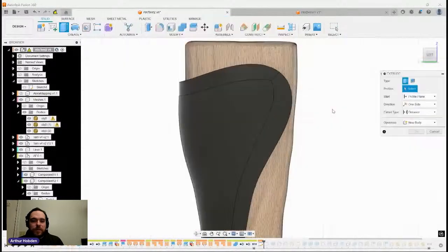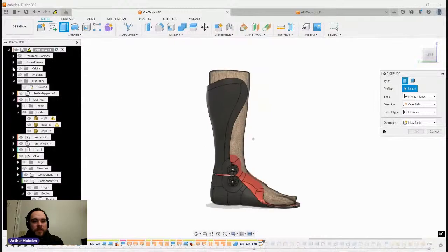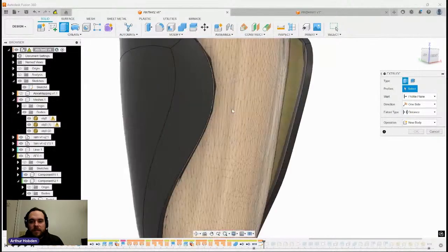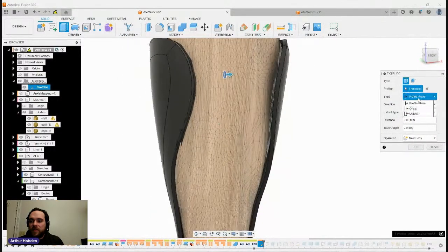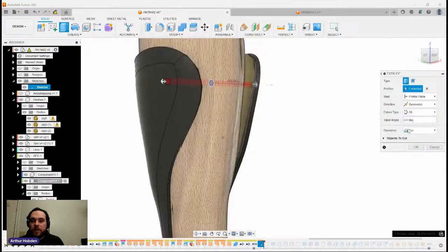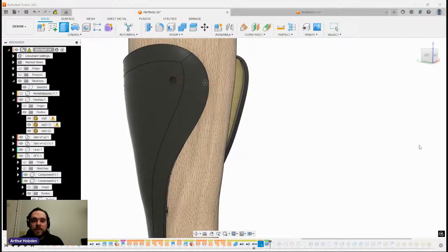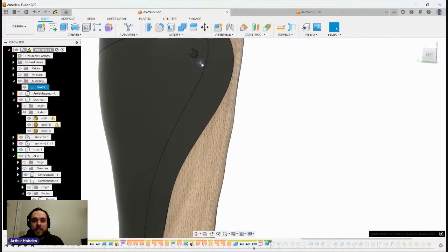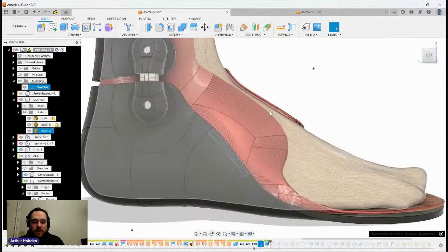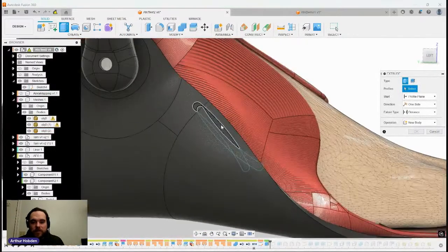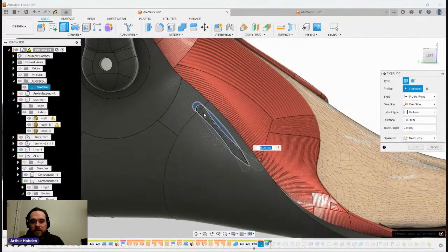So now that we have those mapped out, let's turn on our sketches. Let's first just punch this symmetrically, distance through all, and just punch that hole right through. Nice and easy. And again, if we need to move that, now that it's done, we can do that. Same with these. Hit E on my keyboard to extrude, holding down Shift. Nope, this one. There we go.